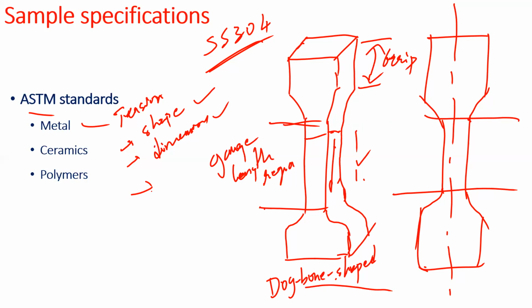What we are doing is uniaxial testing. So typically there is no external pressure; the external pressure is simply atmospheric pressure. Sometimes you also put this sample in a pressurized environment. That is called triaxial testing. What we are doing is pulling the sample along one axis, so it is uniaxial testing. If you have triaxial testing, then there will be more parameters involved. Can I write it clearly?